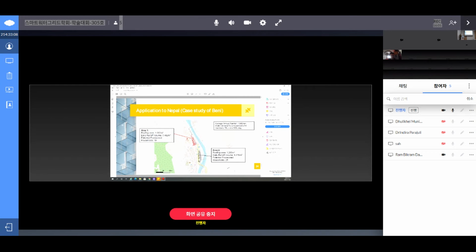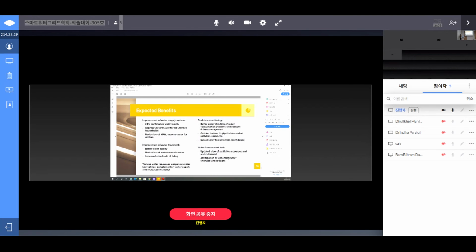So by doing a very simple calculation, and that's just an example really, you've got your average annual rainfall, which is that much, as we mentioned earlier. If you assume that your water demand for a household of 4 people is approximately 300 liters per day, so 75 liters per day per person, then even applying this to very small areas in Beni, you could still have a few households which would be provisioned by this rainwater harvesting technology. So that's an option which also needs to be investigated.